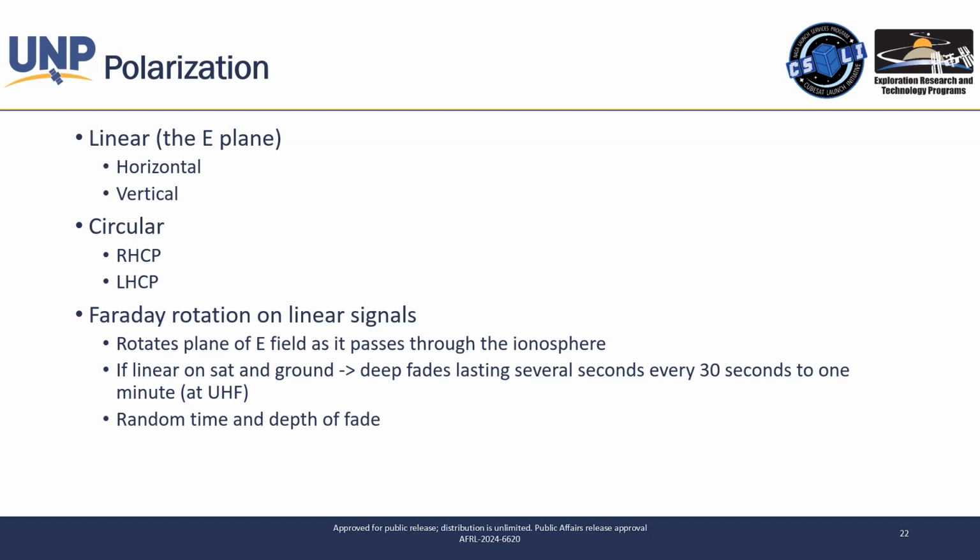When you align an antenna, you want to align with that polarization. If you have, for example, a vertically polarized wave and you're trying to receive it with a horizontal antenna, you're not going to receive anything, right? It's going to induce no current on there because the electromagnetic field at that point in space is completely orthogonal to what it can induce in that antenna. Another type of polarization we use is called circular. Instead of oscillating the electromagnetic field in one straight line, it alternates, basically. It does it in a circle, right?